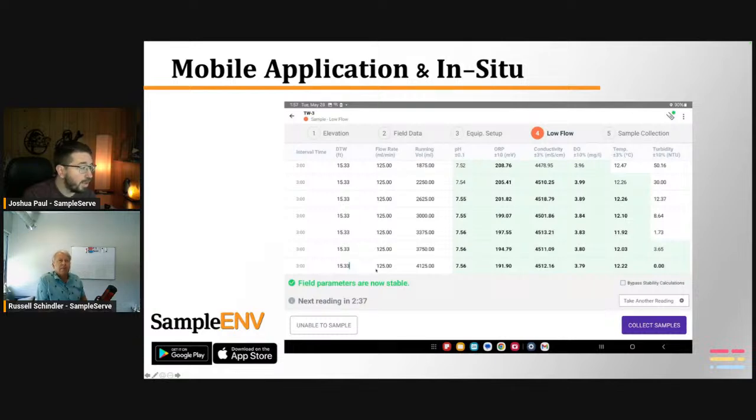Now, you were mentioning before about getting that depth of water automated as well. So if there are any manufacturers out there that are interested, there's a product that I've envisioned that I think would be great. It's a water level tape, with all the measurements on it for doing a typical groundwater elevation measurement, but having an integrated pressure transducer with Bluetooth connectivity up on the reel.